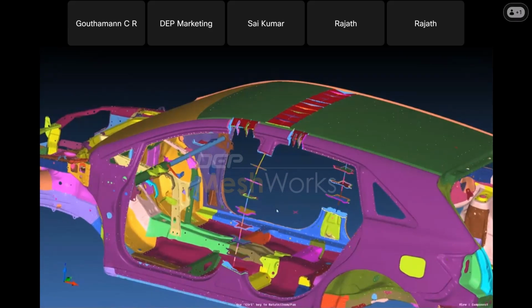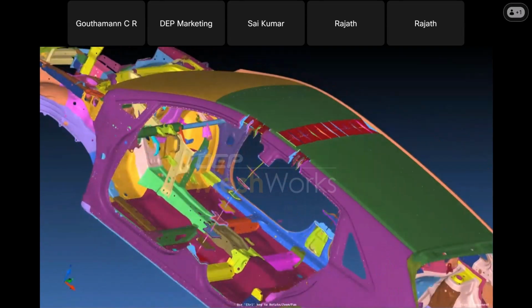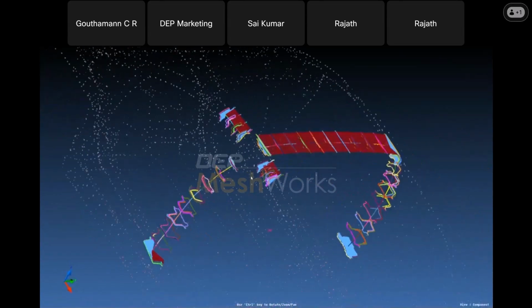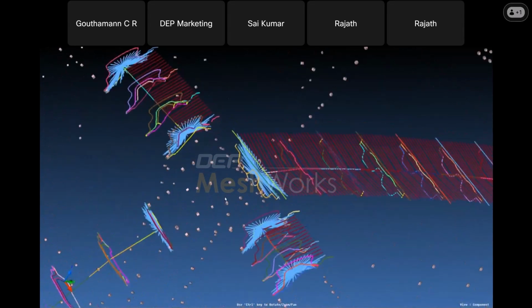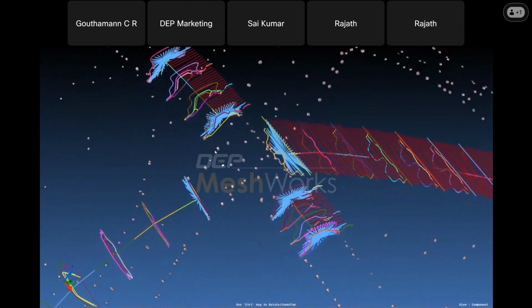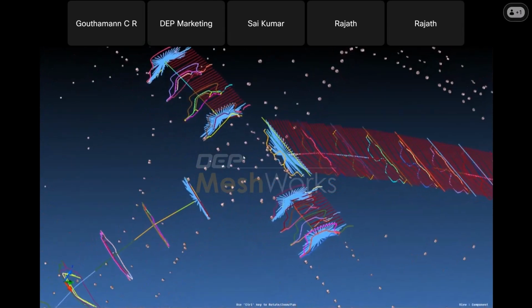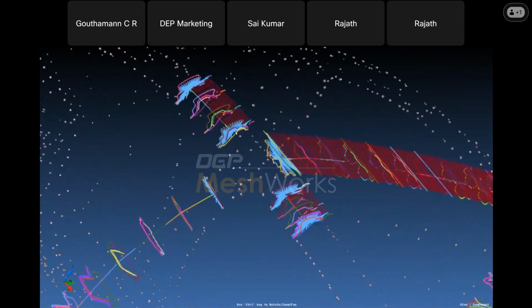So next, I'm going to proceed with the joint creation. We already converted the sections into beams, and now I'm going to show how we can create joints using our ROM tool. For this, in this case, I'm going to show this particular region where we have 4 sections, and we need to create a joint between these 4 sections here.